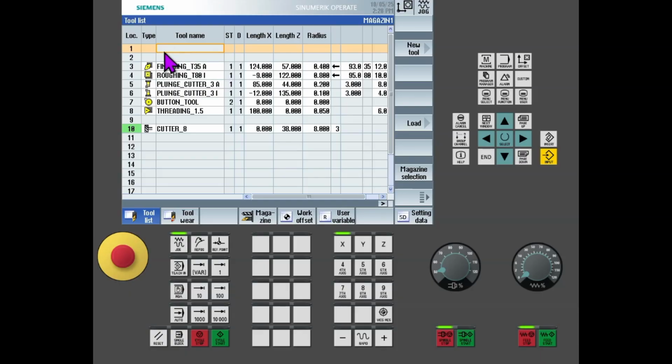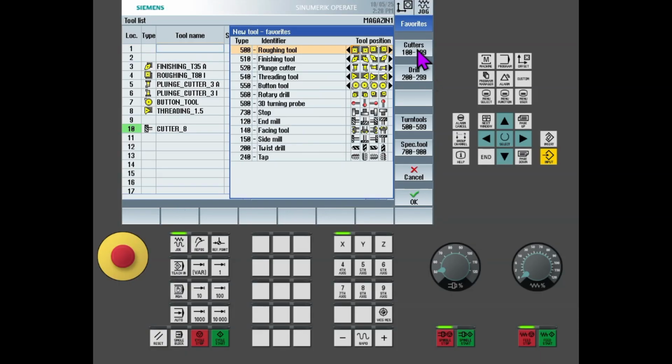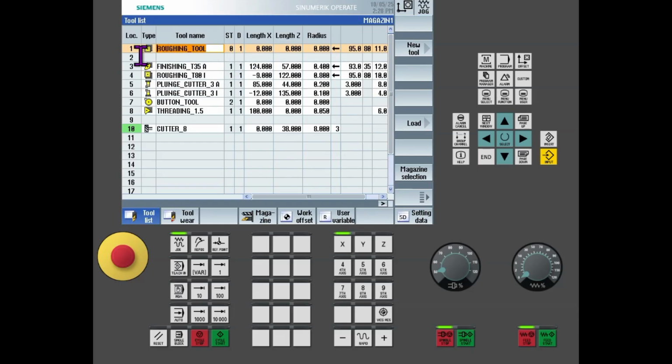At position number one, location one, I'm going to create my tool. For creating the tool, you click on new tool, then choose your tool. Our tool is the roughing tool because PCLNR is a roughing tool. And out of these cutting edge positions, you select the first one, then press OK. Then give your tool name. I'm giving PCLNR 2525 M tool. Then press input.